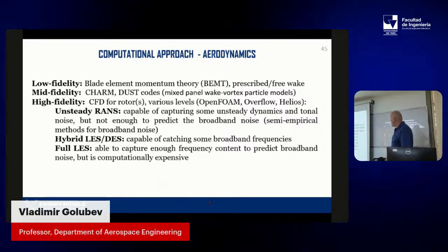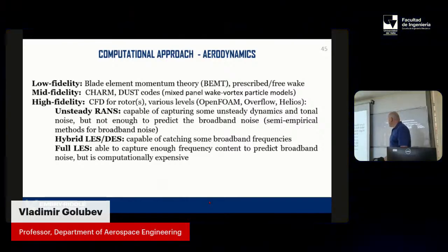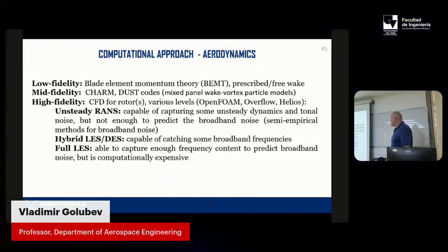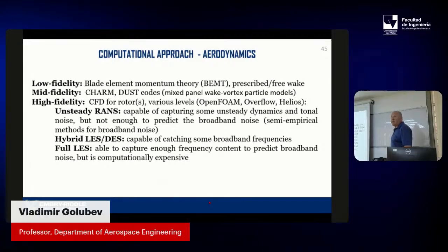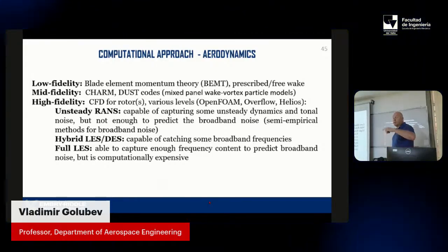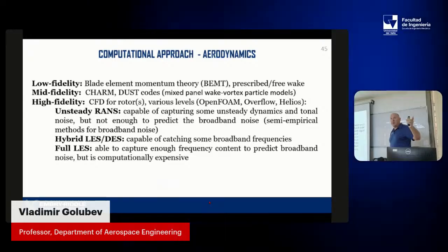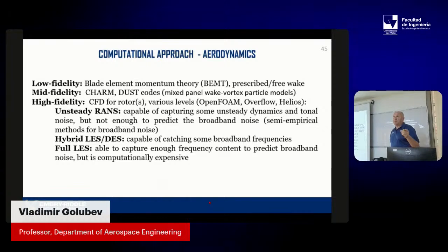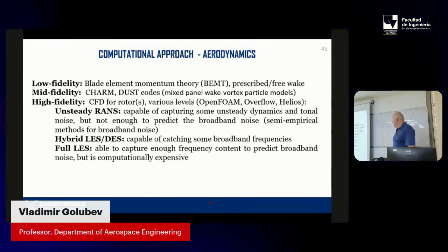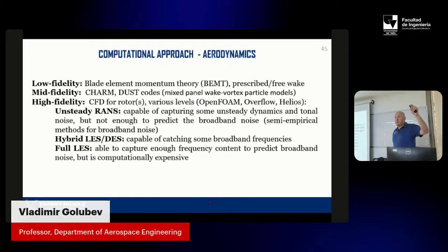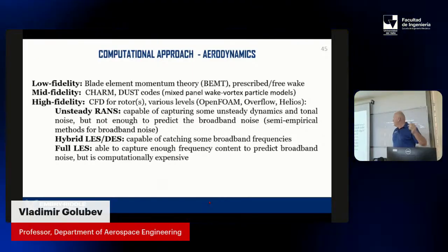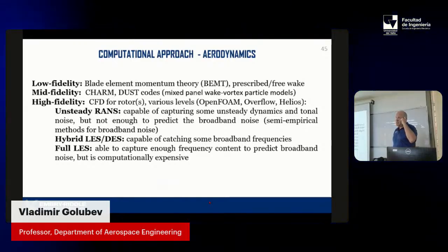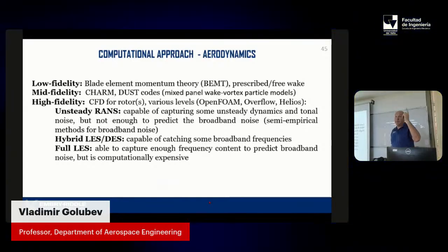We use this for semi-RANS, hybrid LES, and LES. These are the biggest challenge. I mean, it's very expensive. But that's what you need to use for many cases, particularly for broadband, because broadband relies on how well you predict the dynamics in the boundary layer, and it all requires LES because it should be a wall-resolved simulation. So you resolve the entire boundary layer. And with LES, you have to have y-plus around one, which takes a horrendous number of grid points, which takes us to months and months of computations,